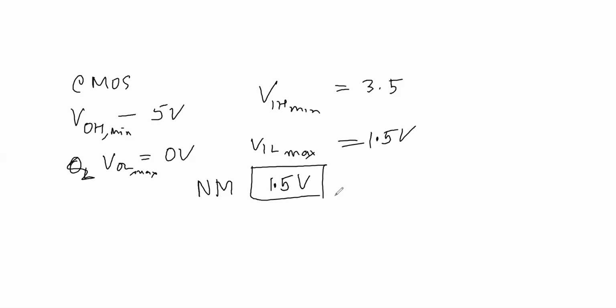The question is, what do we do in case of tri-state logic? Tri-state logic only tells me that the node is neither connected to VDD nor to ground. We will take up a tri-state circuit and discuss it. It is a high impedance node, so the voltage cannot be predicted on that node because it is not connected to any source. We'll talk about it.